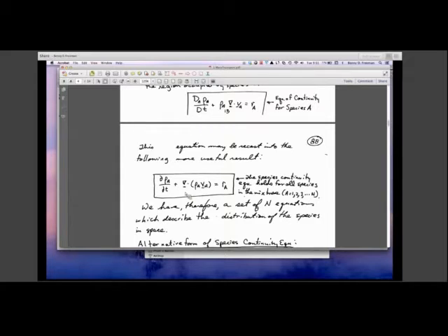What does the divergence mean? You know, that little triangle outside of the divergence of rho A times V. What does that little triangle do? So this is just the mass flux. What does the divergence do to that term? Is it something nasty? So Rika says it's taking the derivative with respect to the x, y, or z coordinates, and that's exactly right.